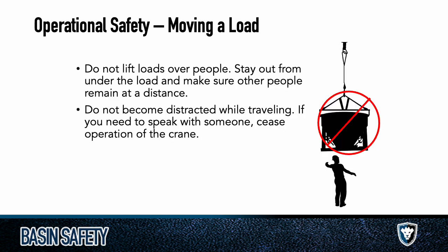So, we call these suspended loads once the lift is engaged. Once you have tension on the lift line, we have a suspended load at that point. No part of a person should be underneath a load. Not a finger underneath a load. Not a finger, not a foot, not a head, not an arm, nothing.